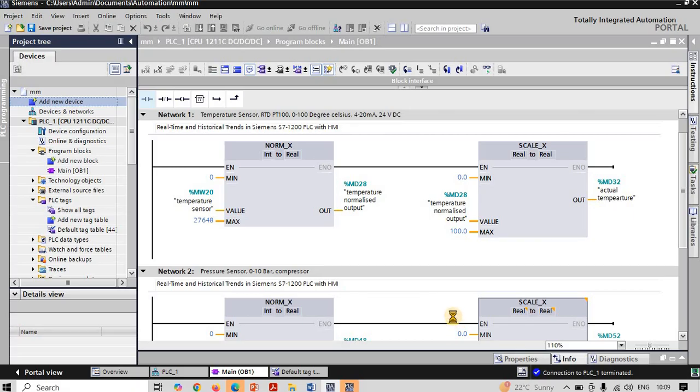and you get a pop-up wherein you can check the settings of the HMI screen. Means how many screens you want, right? Everything you can change. Okay, if you want to go with the root screen, you can go with the root screen also. If not, then you simply have to untick the options. I will show you which option you will have to untick.